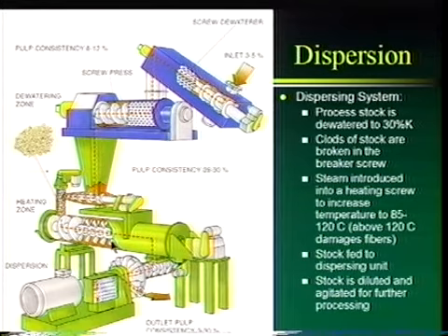Okay, so then what happens next is the heated pulp from this heating zone right here will fall down into a feed screw, and that feed screw is going to push that in to right here, our disc disperser. So we've got our disc disperser here, and then the outlet of the pulp comes this way. And what we're looking at is a pretty big motor right here to run that disc disperser.